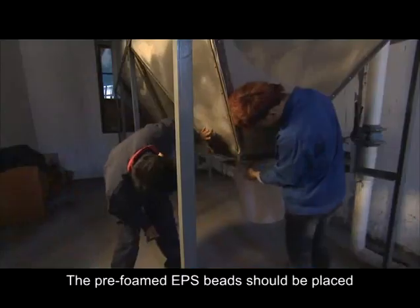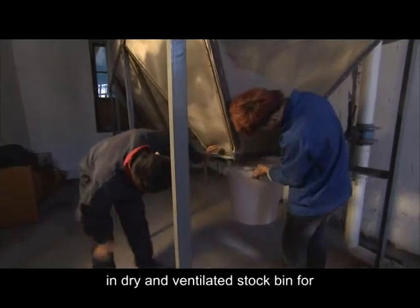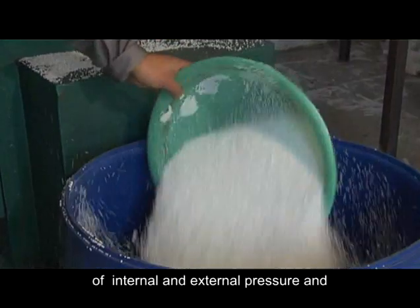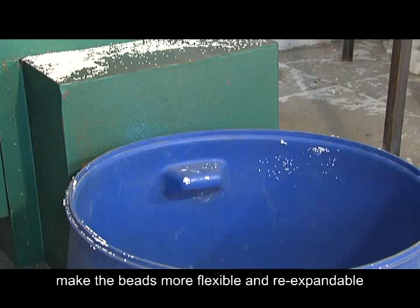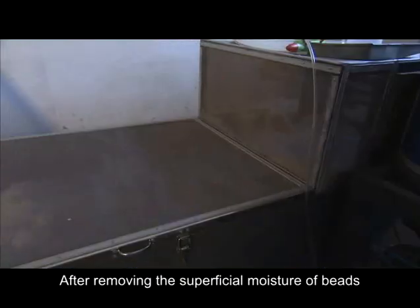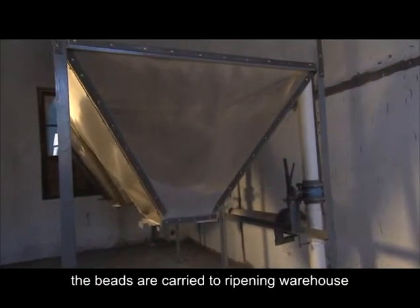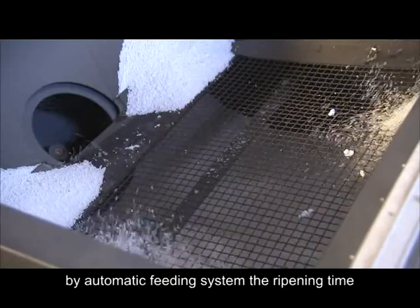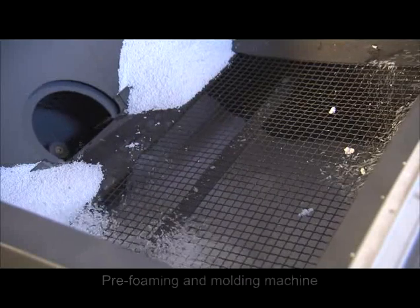Ripening. The preformed beads should be placed in the dry and ventilated stock bin for a certain time to maintain the balance of the bead's internal and external pressure and to make the beads have flexibility and re-expanding capacity. After removing the superficial moisture of beads, the beads are carried to the ripening warehouse by automatic feeding system. The ripening time is about 8 to 48 hours.